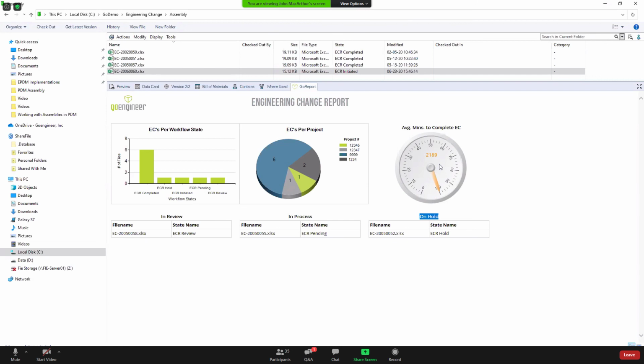On the performance side of 2020, one of the main things that corporate SolidWorks identified as a performance problem was the PDM add-in, while you had it live open in SolidWorks, was constantly talking to the database for information, and that constant traffic was causing some performance lag. So in 2020, they've found a way to dial back how often it's hitting the DB for that metadata information, and that's caused a pretty significant performance gain while working with data inside SolidWorks.